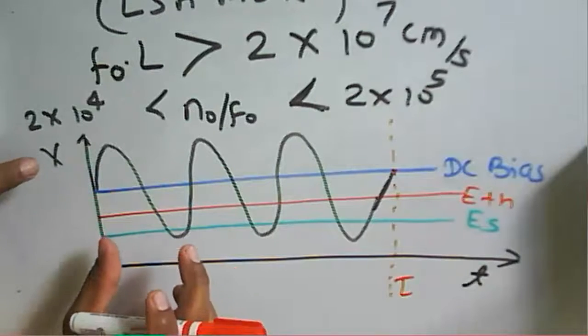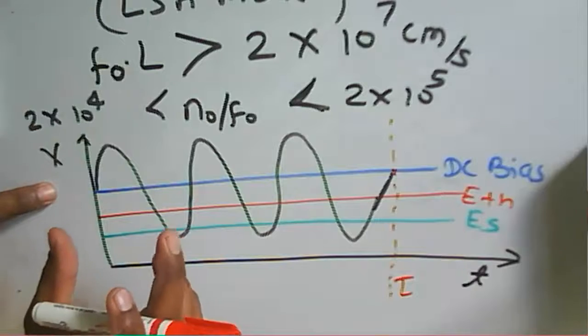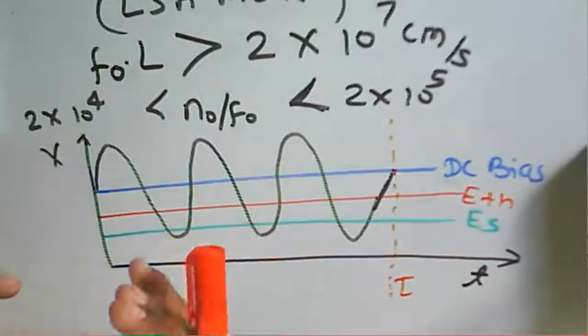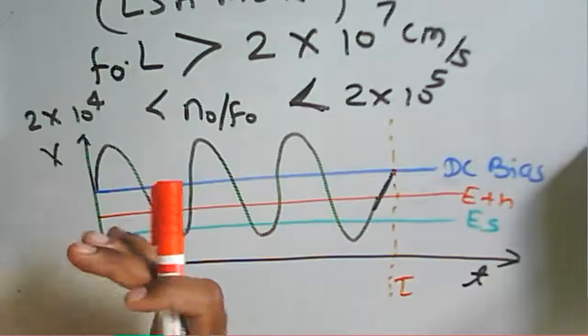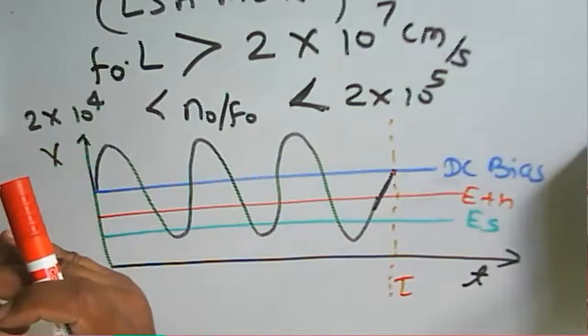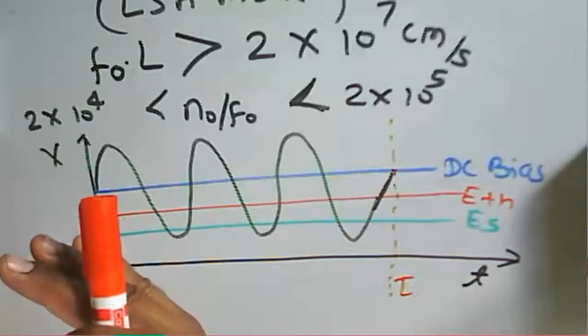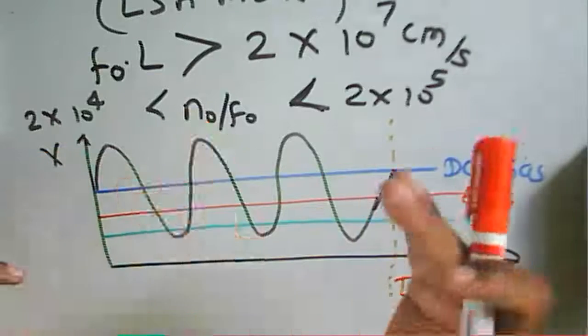For any given diode, accumulation of charges takes place near the cathode, then a domain grows and moves forward until it reaches the anode.